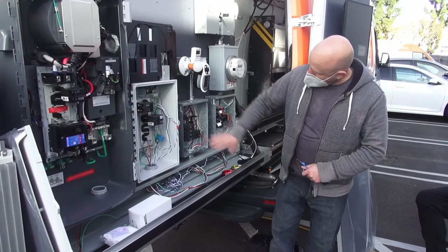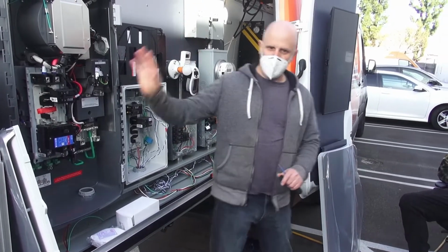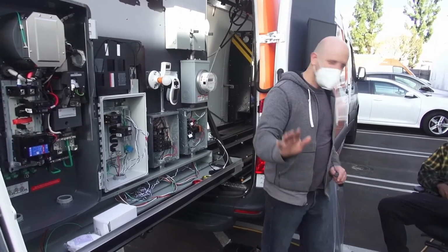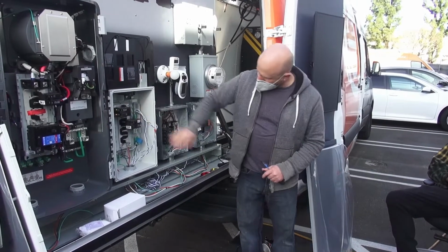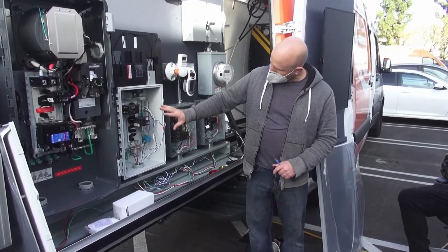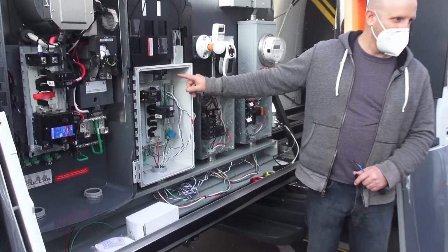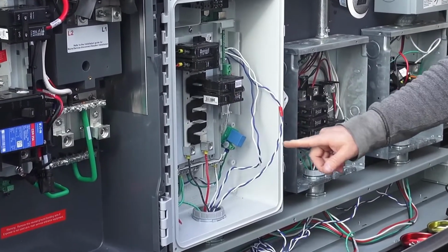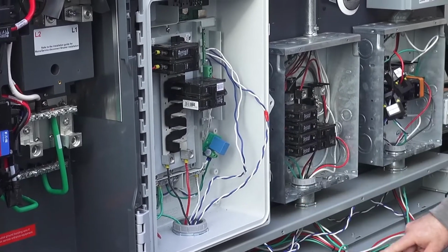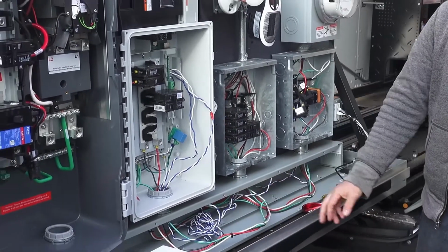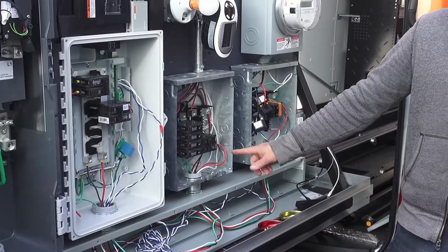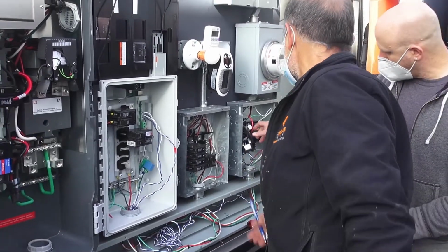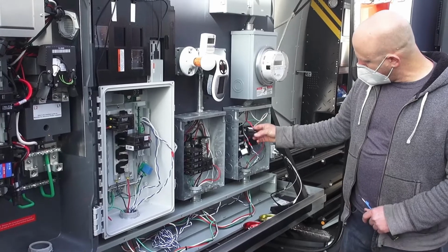And the Envoy, right now, remember, I know we have a lot of equipment, but right now it's just a solar system, just grid tied. That stuff doesn't exist yet, right? So I've got my PV breaker here. My Envoy is powered. This is my Envoy or my IQ gateway, same thing. We're changing the names. It's powered right here. You hooked up solar, where did you put the solar breaker? Bottom right-hand side. Oh, this is the solar breaker? Okay, cool. There's the consumption. So consumption CT goes on the load lines.